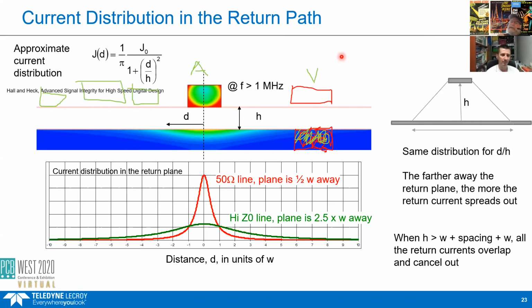It's just that, can you really guarantee that the switching noise I've got is not going to be seen by an asynchronous bus somewhere? I see this a lot in I2C and SPI buses, where they're lower frequency than the clock, and so I'll have switching noise due to other signals switching at a higher data rate or higher clock frequency, and they will give me noise in the I2C data or clock lines, because that's such a wide time interval for the I2C and the SPI compared to the clock edge. I'll have multiple clock edges switching inside there.